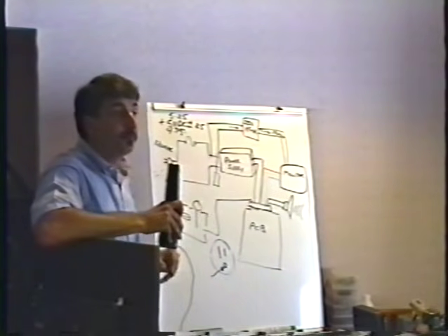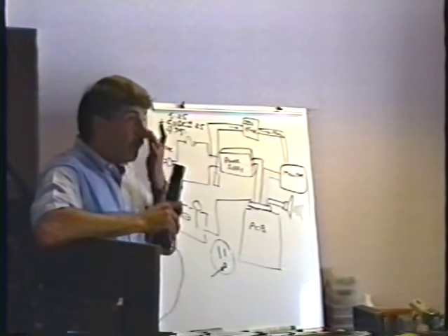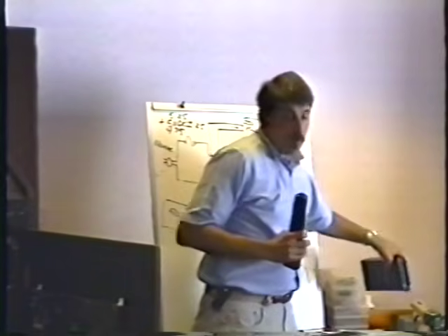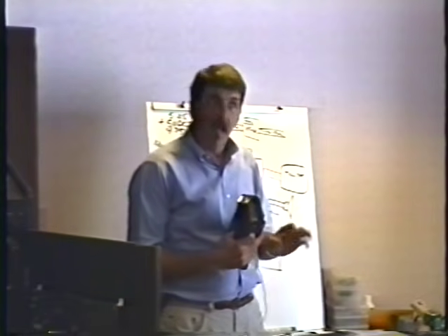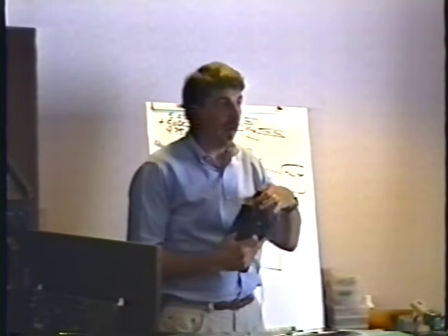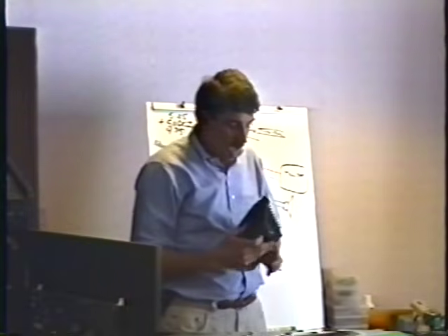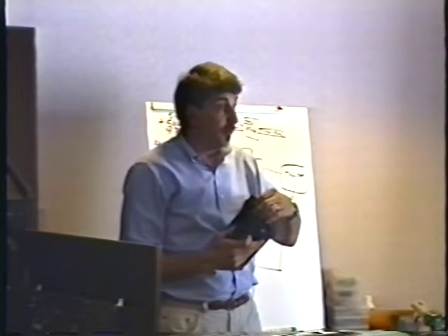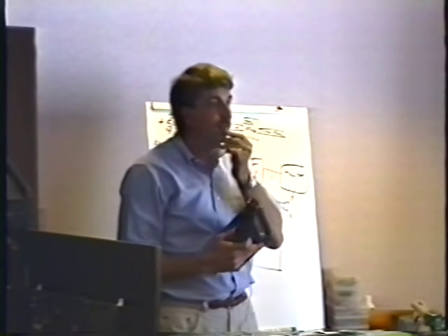Yeah, Ken. Is there any danger in adjusting that real fast too hard? You know, what if you're just way up high real fast, and you go way too high? Yeah, that's bad. Most power supplies are designed so that you cannot, even at maximum, go dangerously high. But I wouldn't trust a power supply at all. You never go, hey, let's see how high it goes. With the meter connected, never adjust this without a meter connected, by the way. But with the meter connected, just slowly bring it up or down. I wouldn't mess around too much.